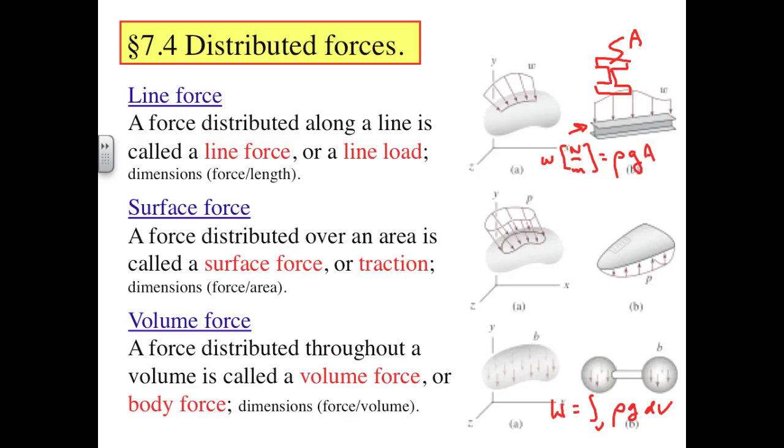If we go back to our airplane example and look at the airplane from its nose, then each wing looks like a cantilevered beam built into the fuselage. If we look at a wing from this perspective as a beam, it's a beam with a tapered geometry, deep at the fuselage and tapering to a much smaller width at the end of the wing. If we replace the pressure differential with a line load by multiplying through by the thickness or depth of the wing, then with a uniform differential pressure, the line load will be high at the fuselage and taper to a smaller value at the wingtip.